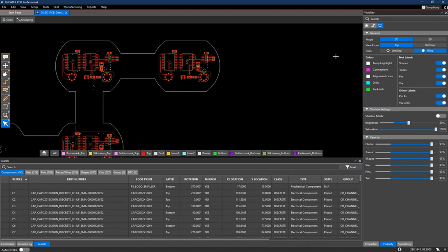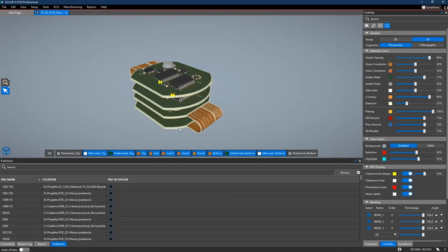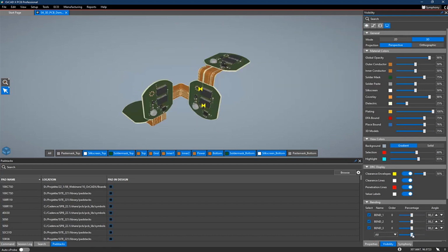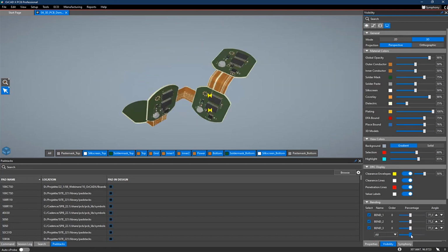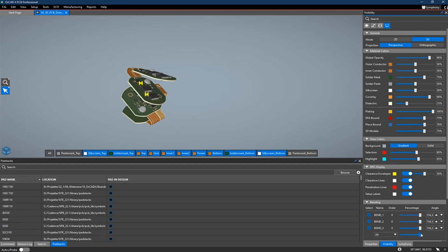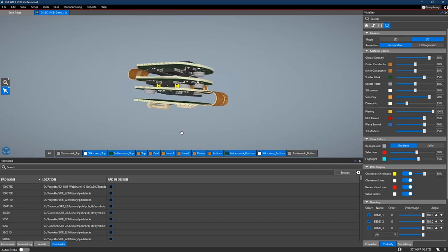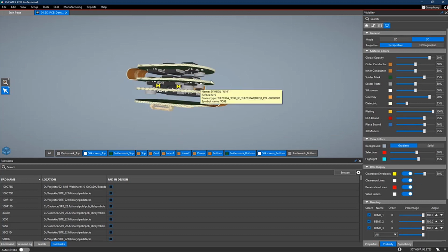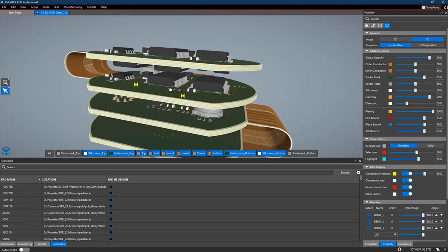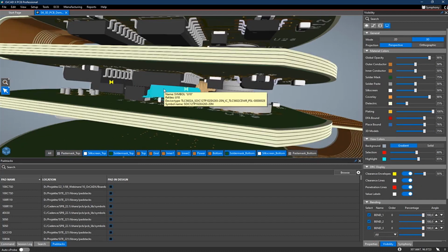First of all, let me show you the switch between 2D and 3D, and you see it's directly integrated. Same canvas, everything stays the same. You are now in the 3D canvas, and you can directly see the spans here. Everything is really fast and smooth. The 3D engine is really powerful in the meantime. What you also see here are some DRC markers, and these DRC markers are coming from my checks I just showed you inside of the constraint manager. Hopefully you can see it. Some of the components are touching each other here, which is not allowed, and therefore I got a DRC here.